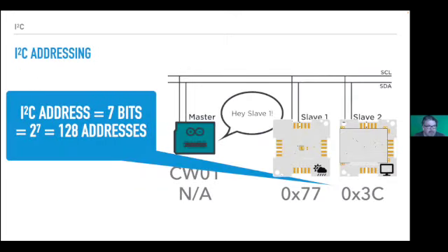So these different devices have addresses. So the master doesn't have an address. That's only the slaves here. So in the case of the weather chip, it's called 0x77, and that's just hexadecimal 77. And the display is 0x3c, so that's the hexadecimal name. You can also write to them in a decimal name. That's just 60. So 3c is the same as 60 decimal. But it's typical in your coding that you use a hexadecimal address here.